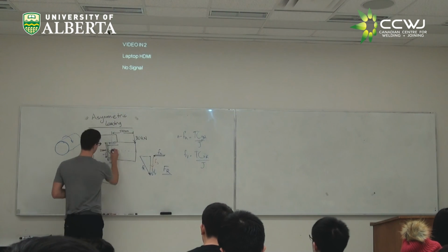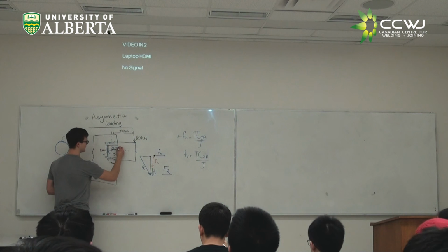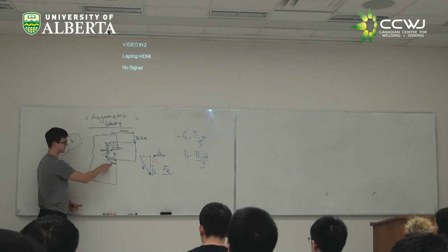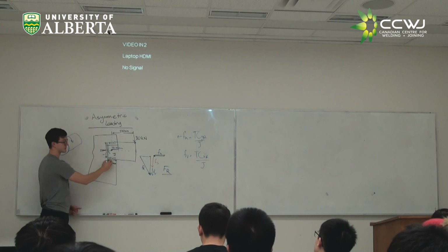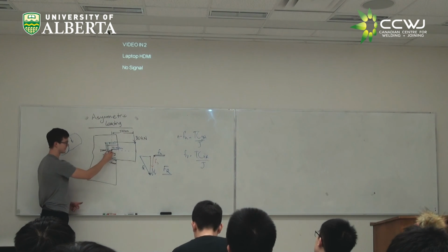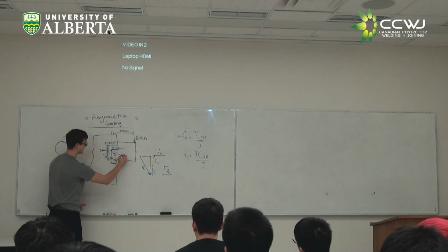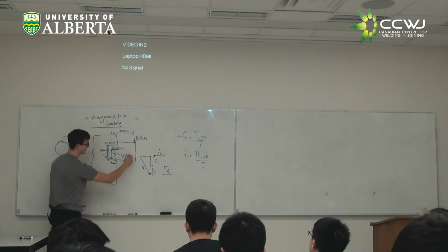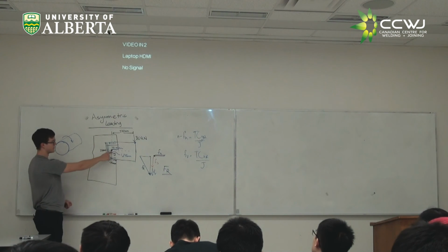So this here, from this edge to the center of gravity, is 93.75 millimeters. That's going to be more than half of 125. This vertical position of our center of gravity, this is 250. Hopefully you guys all can agree. This is getting a bit messy here, but this is going to be 125 millimeters because our weld is symmetric vertically.